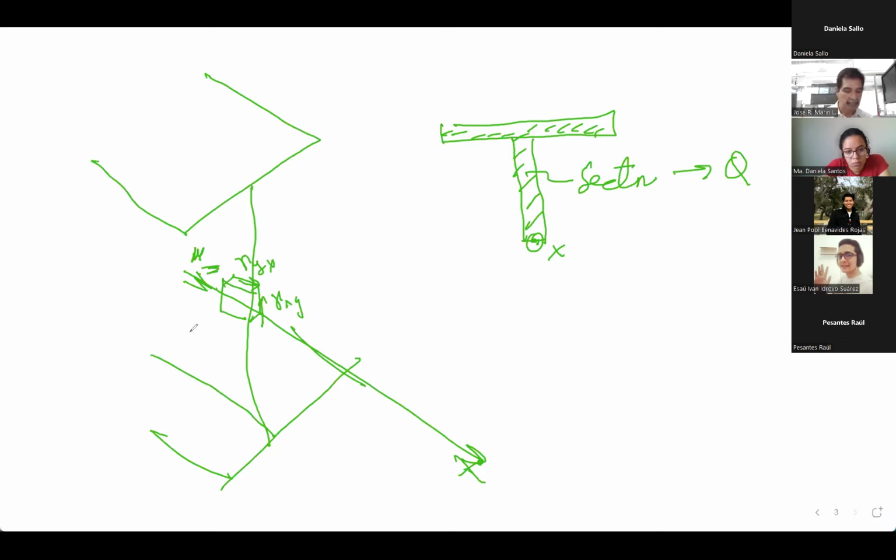Yeah, but see, the problem is that yes, you're right in the sense that in this point there is the maximum shear stress, but it is incorrect in the sense that we don't need to calculate there because of that. We need to calculate there because in that position we have the strain gauges, and we are going to compare the values in that position, not because we have the maximum shear there. Okay.